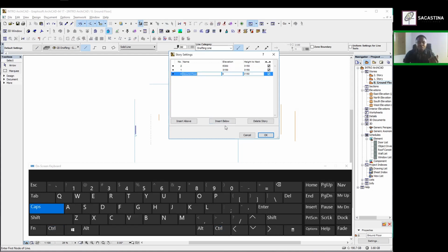You can actually insert a basement floor. For it, let's say you type and you put a name here, basement. You have a basement floor, you can put the floor. And you can change this. Maybe you don't want to call it the basement. You can decide to call it a DPC. Just as an example for us, things that are below the assumed ground level. Let's just put DPC. Let's make it easy, so we understand. Let's make it 1.5 meters, 1,500. And we are good to go.